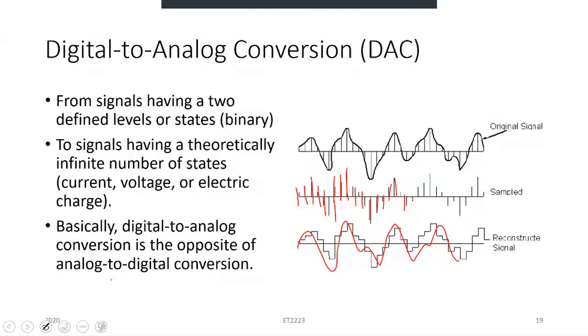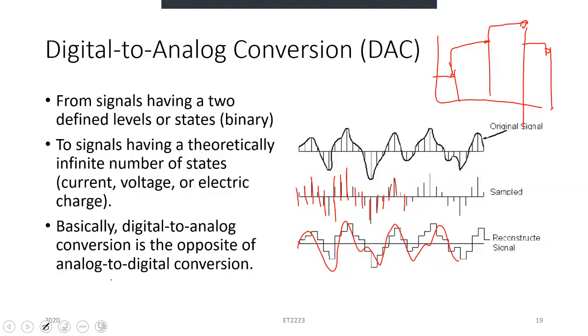If we think about a very simple way of doing this, if we say we have a few points as our sampled digital signal points, we can just hold these fixed values along that period of time to create an analog signal.